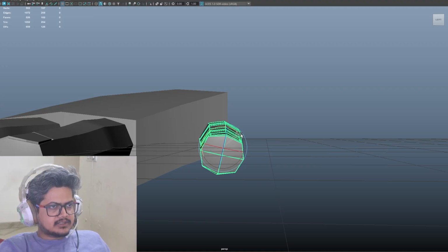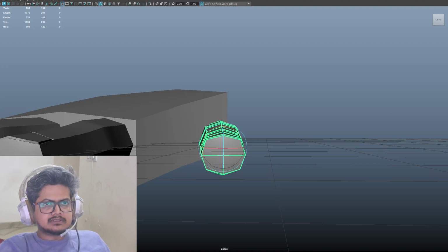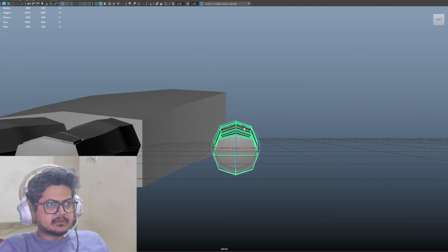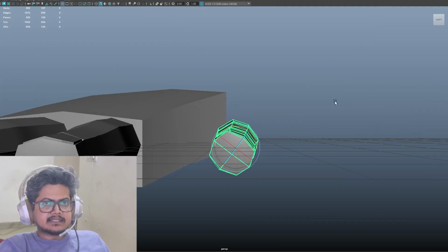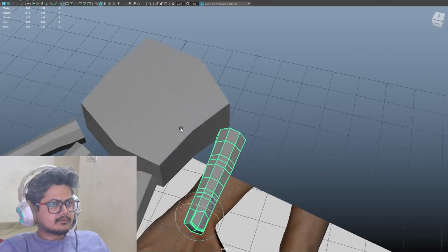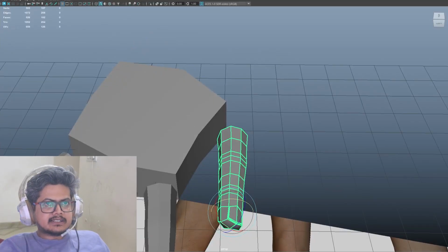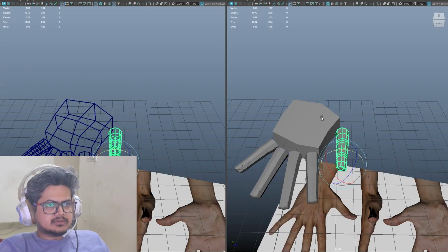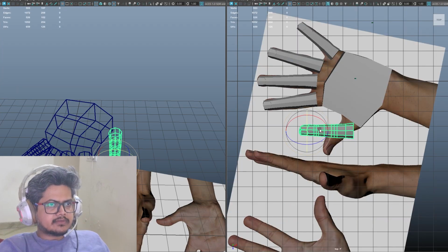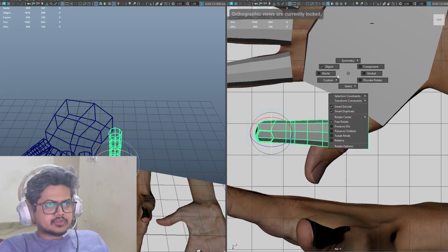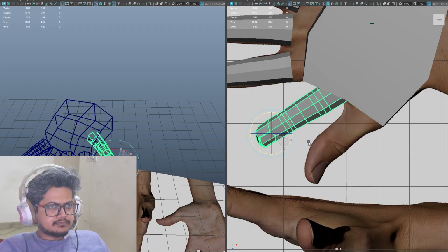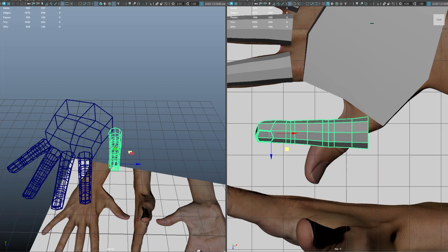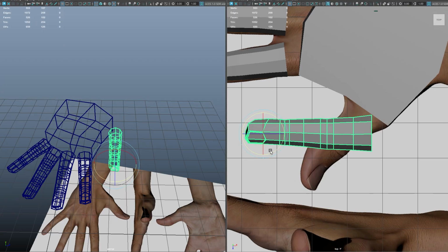First thing, this rotation needs to be somewhere between 35 to 45 degrees, like this. Now you can see it's 35. I'll leave it around, let's say 40. Then I go to top view, switch to world, and try matching it. It almost feels like 45.